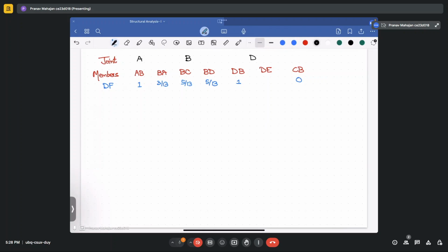So your fixed end moments you have calculated. That value is minus 37.5. Here it is 37.5. It would be 0. Minus 24. Here it is 24. Then because of the cantilever, it will come out to be minus 64. And here it is 0.